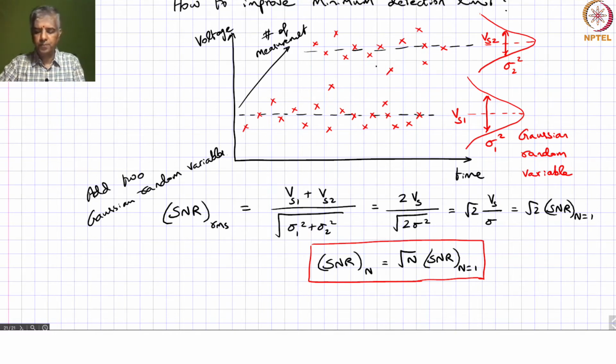Let's say this is a gas concentration. So, the gas concentration is holding at a steady value. If it is holding at that steady value, then you can afford to do such averaging. So, through averaging you are essentially getting this improvement in the signal to noise ratio.